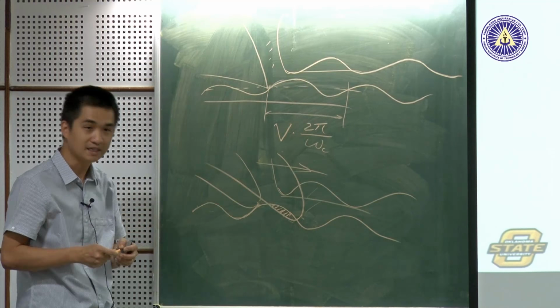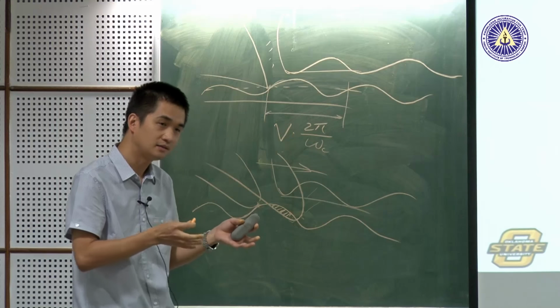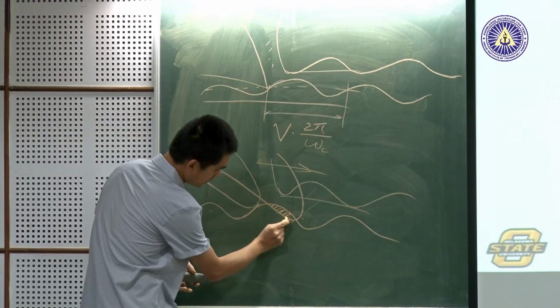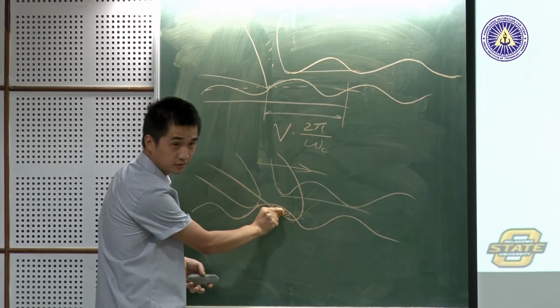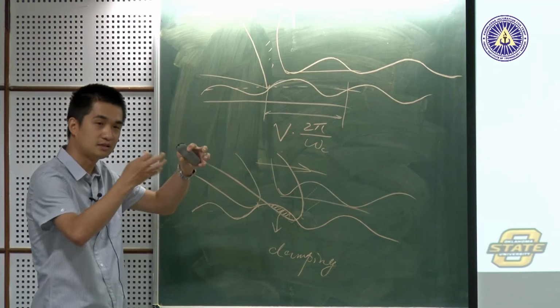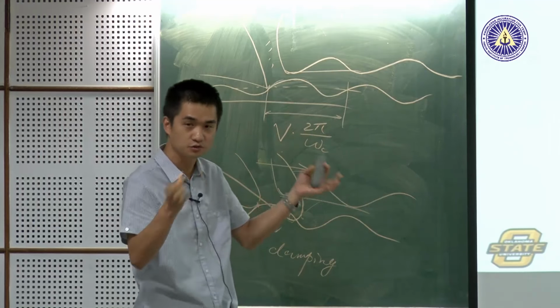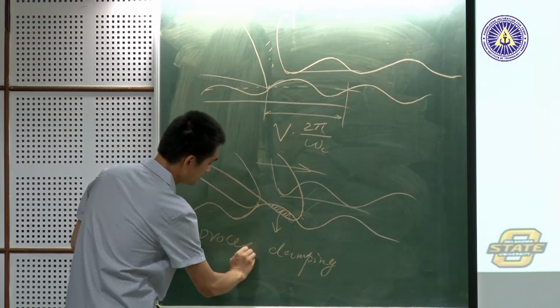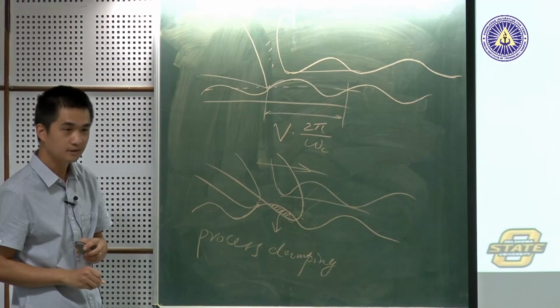From the dynamics point of view, energy dissipation is modeled by damping. So basically damping means energy dissipation. That's why the indentation from the tool edge to the surface is what we call a certain different type of damping. And it's not coming from the material of the tool, not from the joint structure, not from the tool structure, not from the shank-tool structure. It's coming from this process. That's what we call process damping. That's a concept.